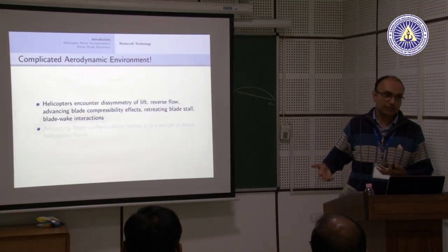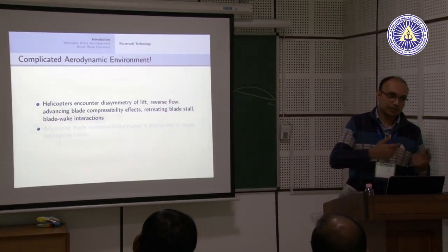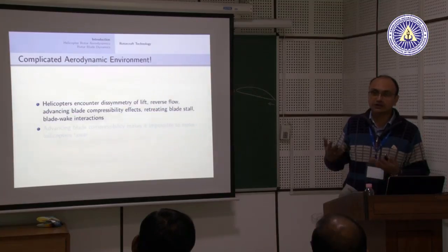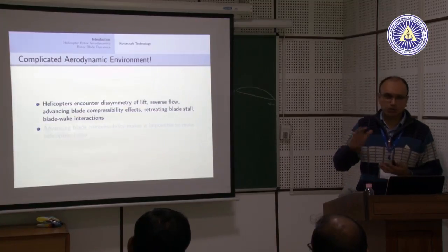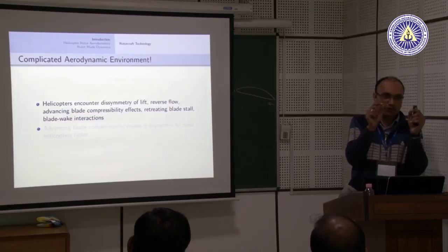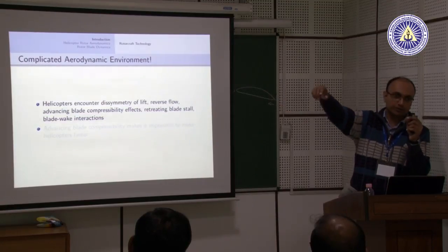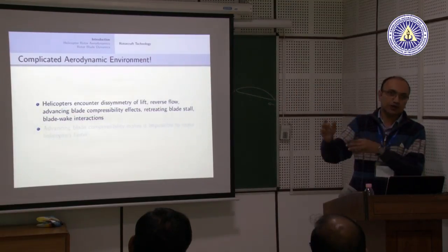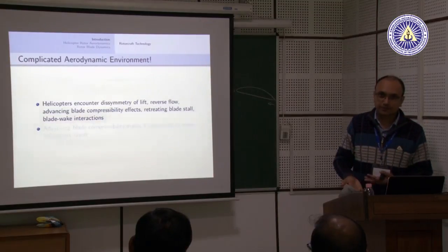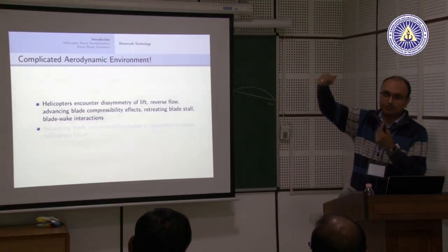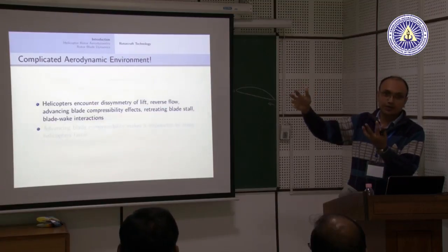Commercial aircraft have a top speed of around 0.78 to 0.8 Mach number. So you see, you have very little room. Your tip speed will go beyond 0.8 Mach number at 0.15 Mach forward speed, because 0.65 added to 0.15 gives you 0.8, which is kind of the limit.